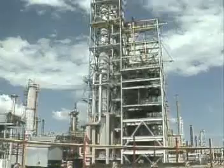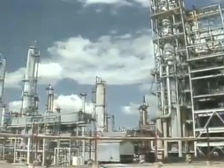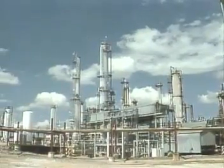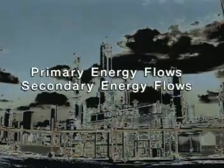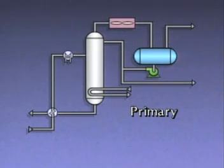For a distillation system, the term energy balance means that the heat that goes into a distillation tower must be equal to the heat that goes out of the tower. The energy flows for a distillation tower can be divided into primary energy flows and secondary energy flows. Primary energy flows are associated with heat transfer into or out of the system.